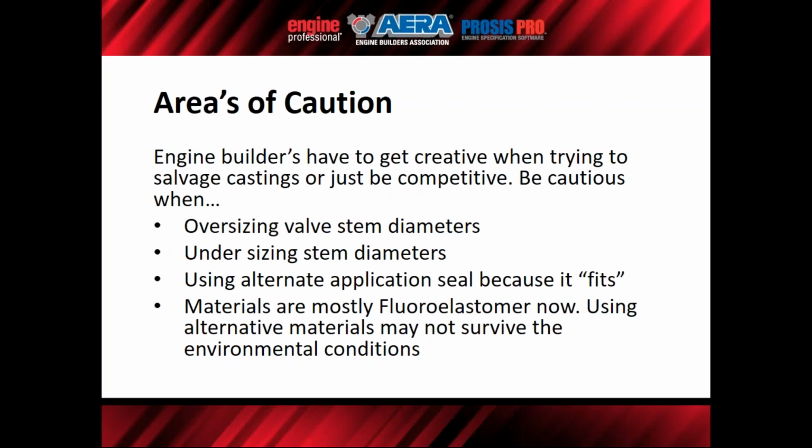Materials are mostly fluoroelastomer now. Using alternative materials may not survive in your particular environmental condition. There's a lot of importing going on worldwide. So maybe somebody doesn't have the knowledge to say, hey, this particular engine is going to have oil temperatures that often do see 230 degrees.